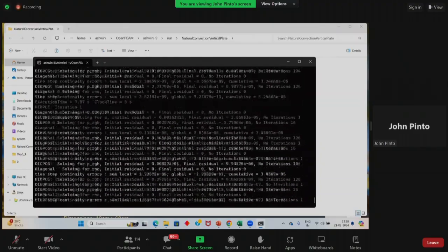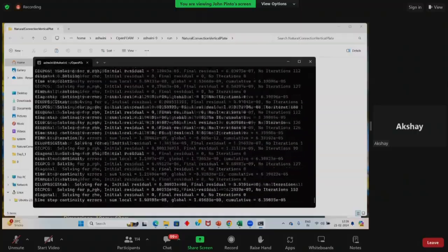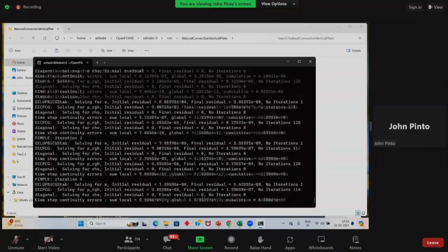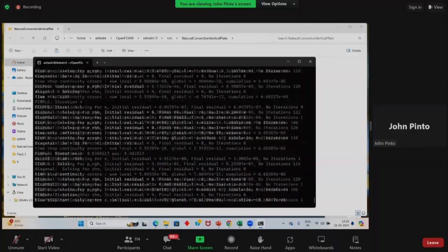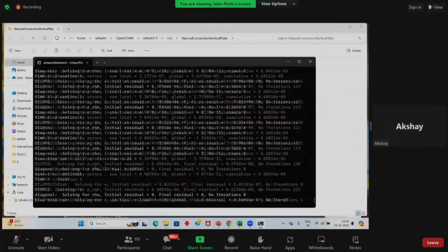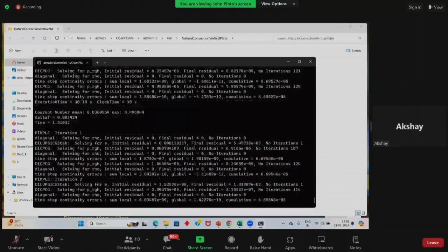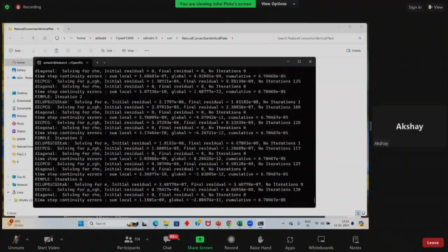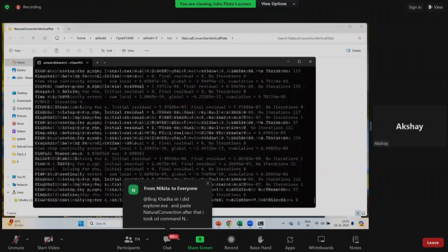Where is this buoyantPimpleFoam solver located? All these solvers are available in your solvers directory, right? In your run, as soon as you type sol, you will get this. It will be under your heat transfer section. If I want to add an equation, like let's say I have to add a term in the momentum equation, something like a del T by del X term, can I add it there?